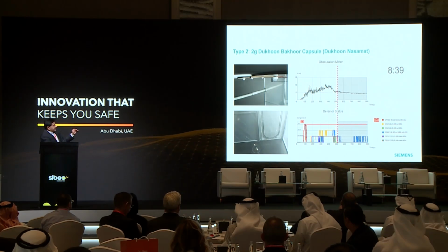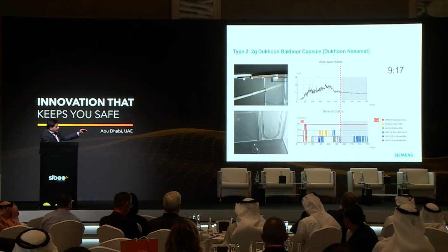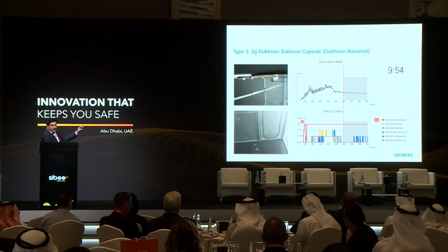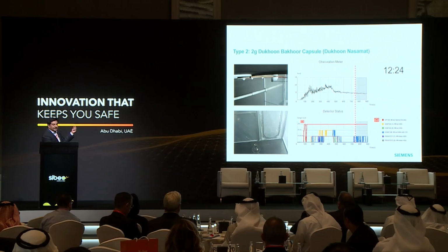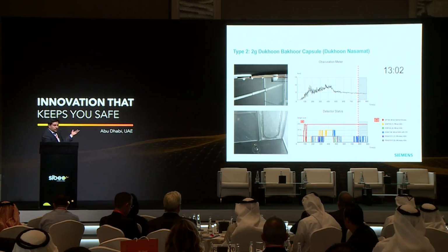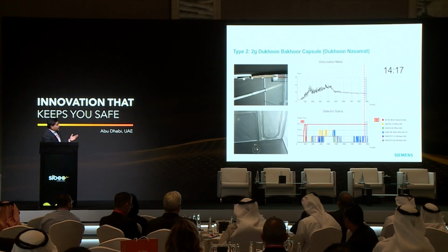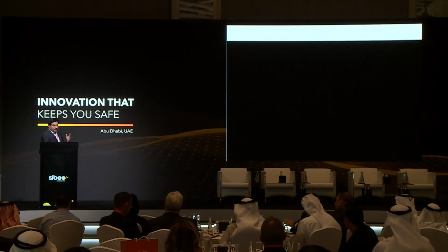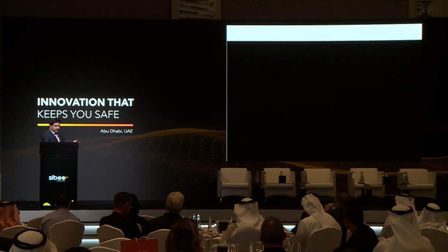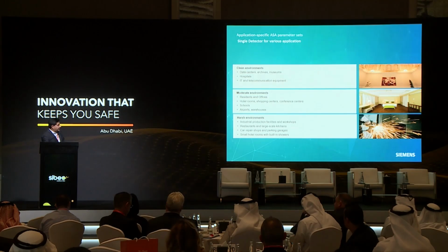But the ASA technology detector picked up a specific signal of pre-warning and warning, but it did not trigger an alarm because it understood that this cannot be a true fire. It doesn't give the element of heat, it doesn't give the required carbon monoxide, and the environment is different. So with this, we had several different tests conducted with the civil defense also in their facilities, trying to see how we can combat these false alarm scenarios.